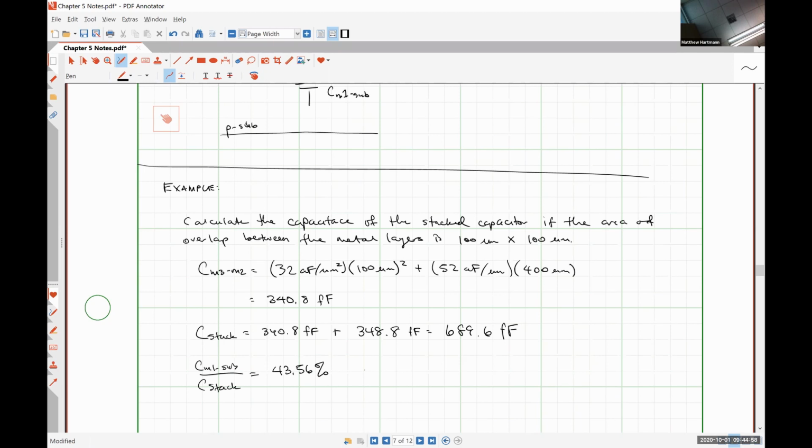So that's, again, as I mentioned above, a tried and true method of minimizing the parasitic capacitance of your metal capacitors, which you may wind up putting in your design because one of the downsides of the poly-poly capacitor is that it's harder to make small capacitance values with it.